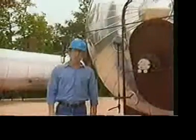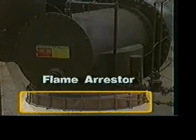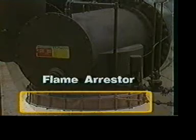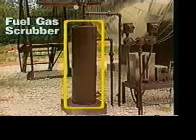In order to operate efficiently and safely, every horizontal heater treater is equipped with various monitoring features and several safety devices. A flame arrestor fits on the front of the firebox. Aluminum vanes disperse heat generated in the firebox to the air. This reduces the possibility of fire outside the vessel.